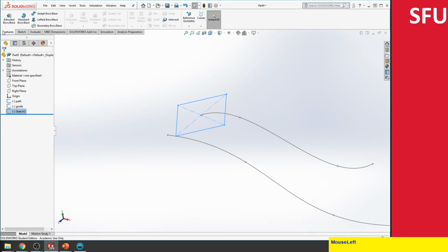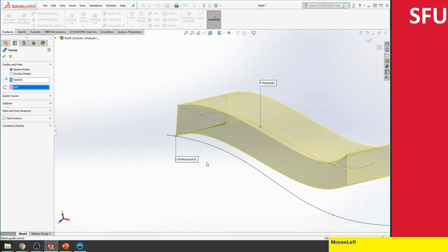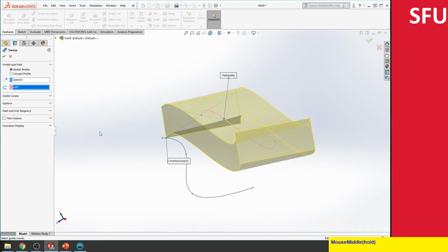And then we are going to do the sweep now. For that we have to go back and click on sweep. We're going to use this as the guide. So we do sweep, and then it's asking me for the path. So I'm selecting this. It looks like it's created the shape. Let's actually see what happens if I select the guide curve over here.